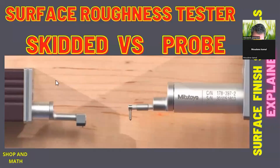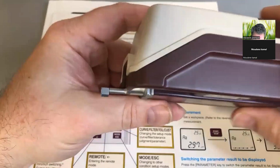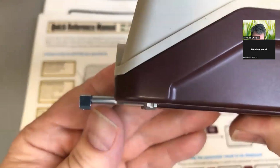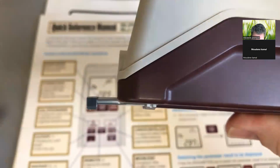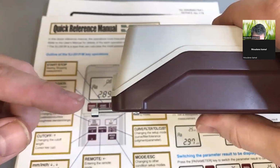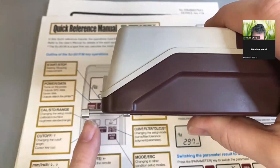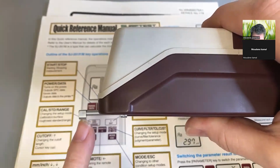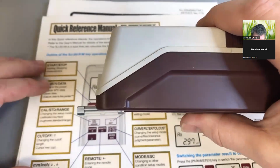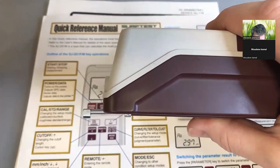Surface roughness tester, skidded versus probe. But what I want to talk more about is the stylus on the end here. If you take a look, you see that there's a tiny little needle sticking out the end there. That tiny little needle is actually what feeds back information into the system. But this is called a skidded type probe because it actually rides on the bump that's here. This can only check flat surfaces. It can't really check tapered surfaces or round surfaces.